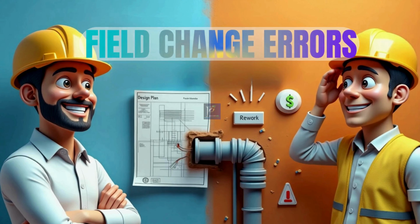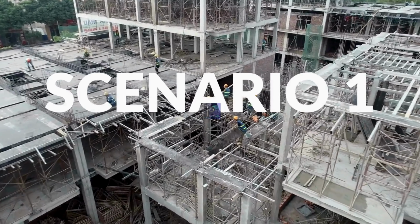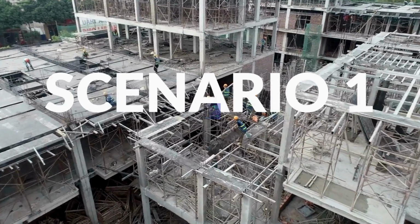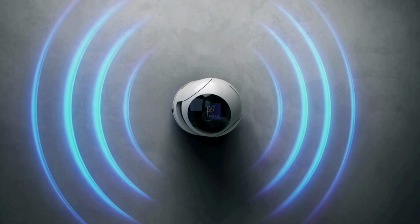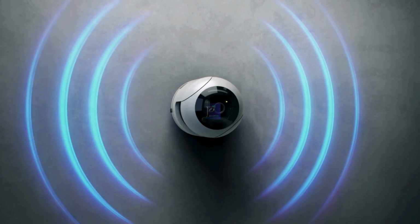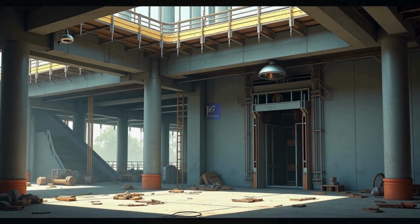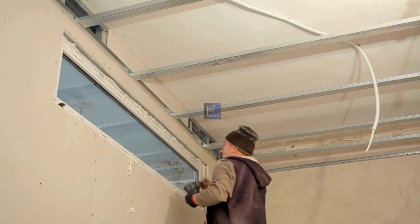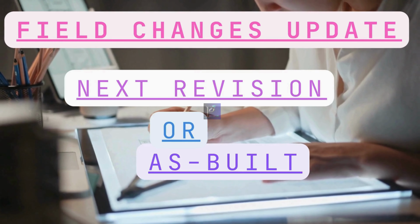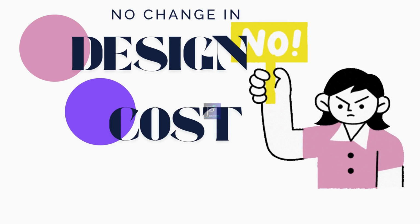Okay, let me give a simple example. Consider a scenario in metro rail station construction involving the installation of a CCTV camera. The objective is to capture the entire view of the station. During installation, only half of the station is covered due to the elevator's position, which blocks the remaining view. So the team decides to reposition the camera to a location where it can capture the complete view. This requires only minor cabling adjustment with zero impact on cost or schedule. The revised cabling route will be recorded in the as-built drawings. Okay, fine. This is a field change. It involves no design change, no cost impact, and no schedule impact.